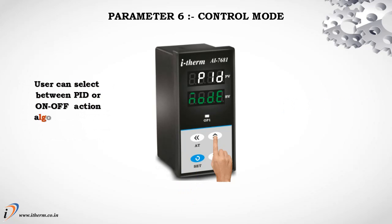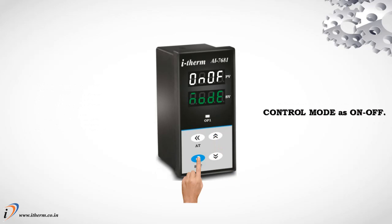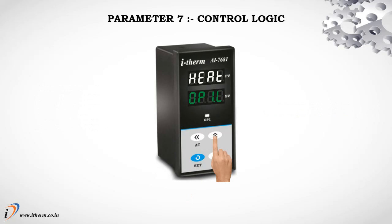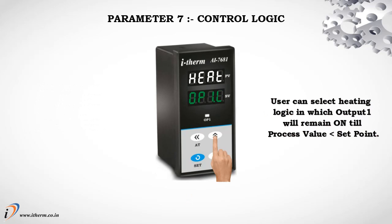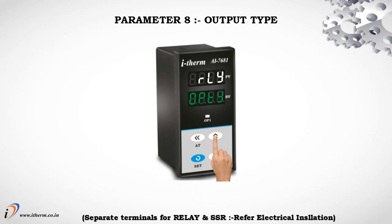Parameter 6, control mode. User can select between PID or on-off action algorithm to be adopted for output. Control mode as PID. Control mode as on-off. Parameter 7, control logic. User can select heating logic in which output 1 will remain on until process value is less than set point. User can select cooling logic in which output 1 will remain on till process value is more than set point.